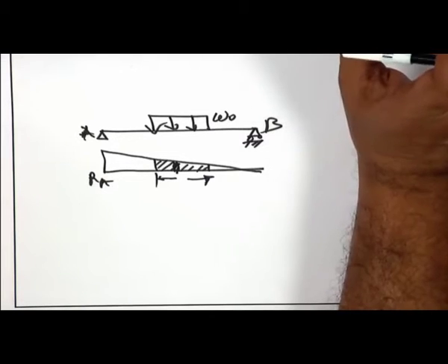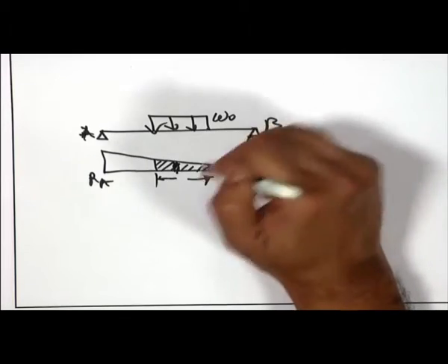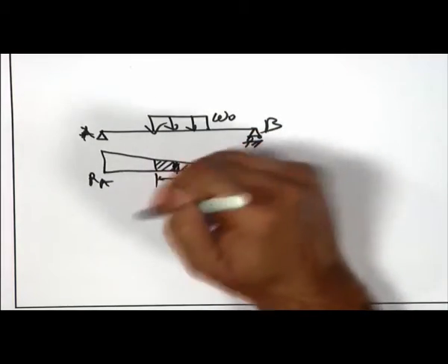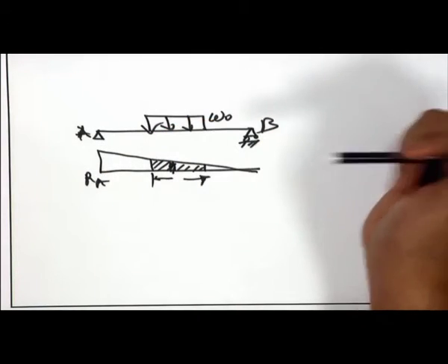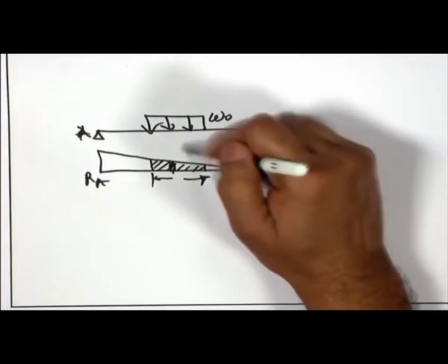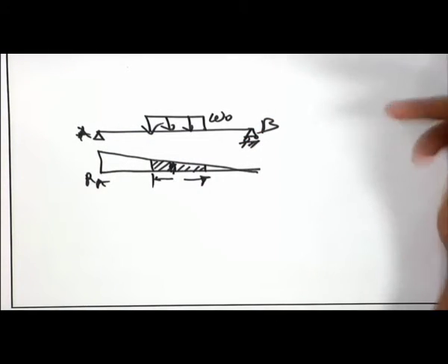For uniformly distributed load, your omega 0 comes out of the integral. So, you are left with the geometric task of finding the area under the curve. Area under the curve is very simple. You can integrate with an elemental area, or you can use the geometry.